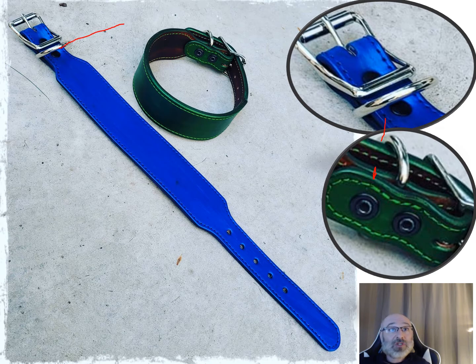So if you're coming up with a force off of your D-ring right there, you're pulling against these two pieces of leather, trying to pull these apart with that D-ring, moving it up. So you do put these in tension rather than just in shear. So with the weight belt, we're pulling across the side. With these dog collars, we're kind of pulling out and putting it right in tension at axial load. So I really do want to make sure I have enough rollover like that. You get a good impact load if a dog takes off, sees a squirrel or something, and you're on the leash. You want to make sure that that's not going to rip out, so you want enough strength with that there. And I ended up doing a double rivet with this as well, just one on each side of that D-ring there to distribute the load.